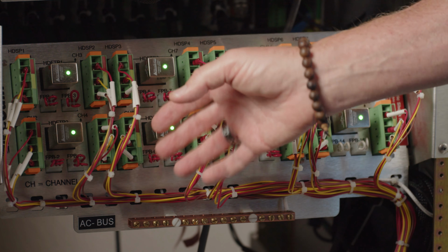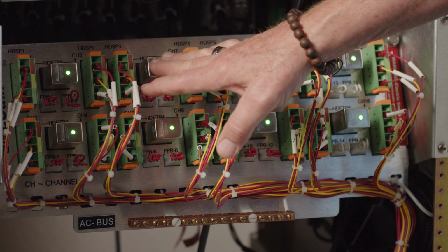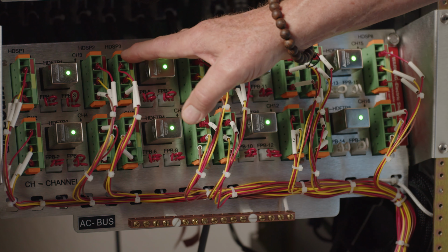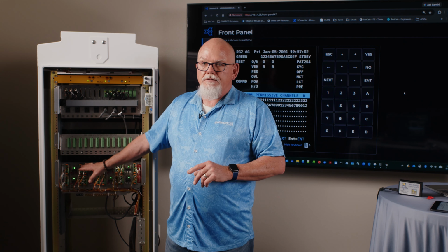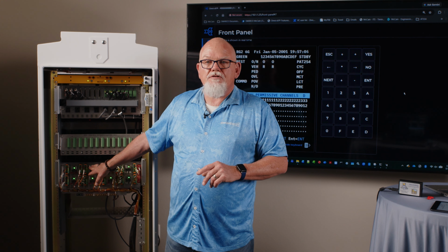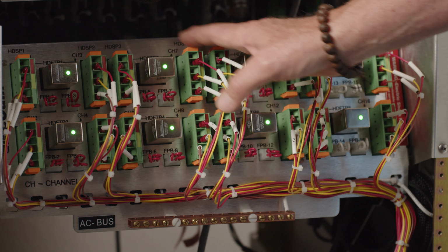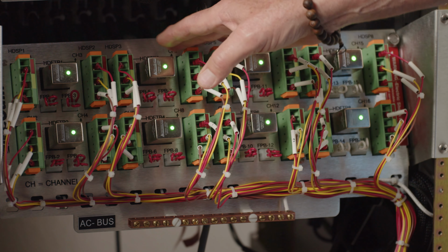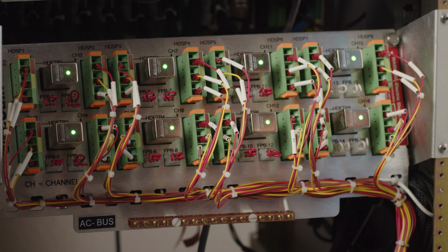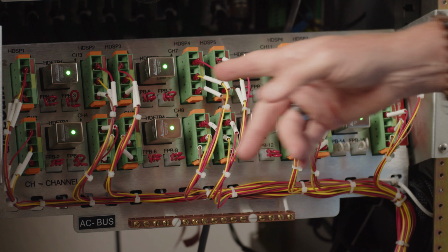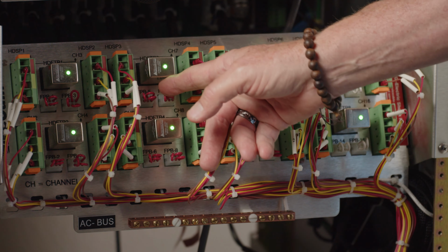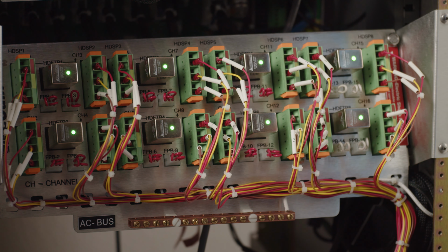This is our field output terminal assembly, or sometimes called a FOTA. And this is all the field terminals. This is the reds, yellows, and greens going out to the field. On this panel, you'll also notice that we have our flash transfer relays. Flash transfer relays are much smaller than you're used to seeing, and they are also metal, and they're hermetically sealed. So it provides a better solution to the old plexiglass flash transfer relays. And the last thing on this panel that you'll notice is we have these flash blocks, these little red, yellow, or white flash blocks. This is how we determine how the intersection is flashed during a flash condition.